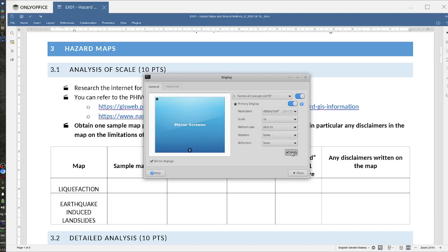This is the geological basis for determining the size of an earthquake, based on the study of Wells and Coppersmith 1994. This study is almost 30 years old, but it is still widely used now, even by PHIVOLCS, I believe. It is mostly still applicable, though it has limitations, of course. There are not a lot of alternative studies for doing this.